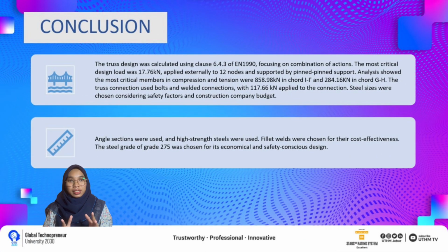To summarize this project, the truss design was calculated using clause 6.4.3 of EN 1990, focusing on combinations of actions. The most critical design load was 17.76 kN applied externally to 12 nodes and supported by pin supports.